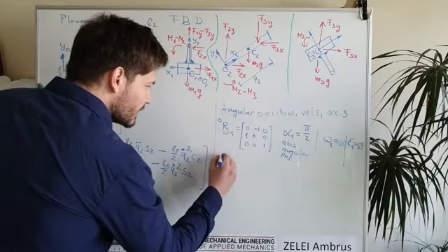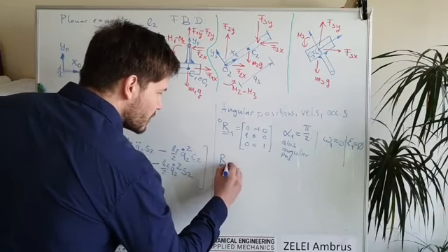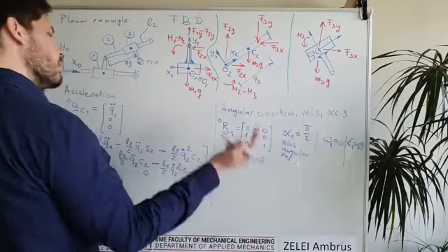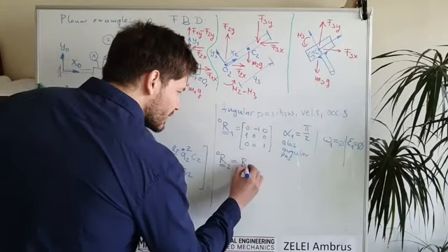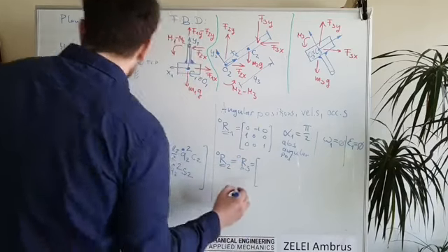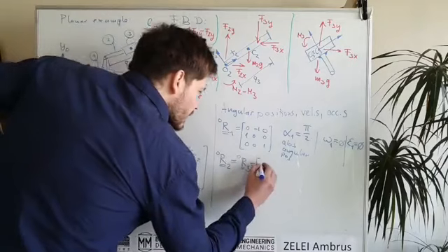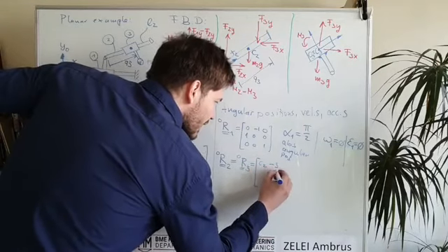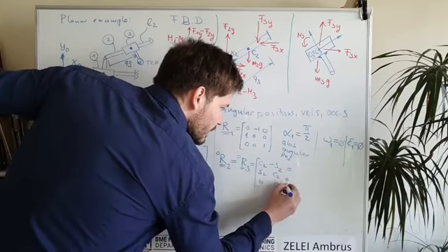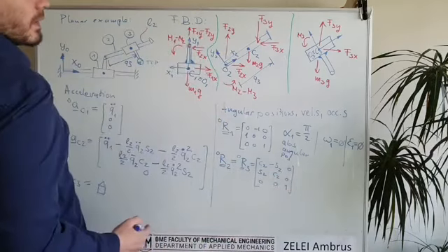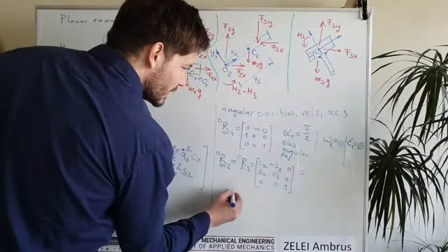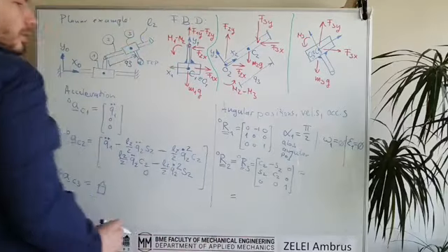And you can take similarly the rotational matrix for the second body. But if you go back, you will see that it is exactly equal to the rotational matrix of the third body. And this is basically cosine Q2 minus sine Q2, sine Q2 and cosine Q2. And there is no rotation in Z. There is the rotation about the Z axis, so therefore this is 0, 0, 1.